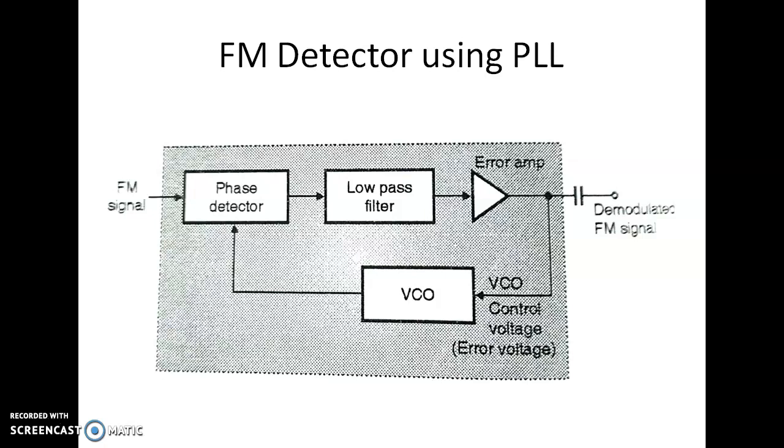The output frequencies of a synthesizer should be very stable. In order to ensure the stability of the output frequency, a crystal oscillator of frequency F oscillator is used. The output frequency of the crystal oscillator is divided by M with the help of the divide by M network. Thus the input frequency to the PLL is F oscillator by M. It is to be applied as the input.